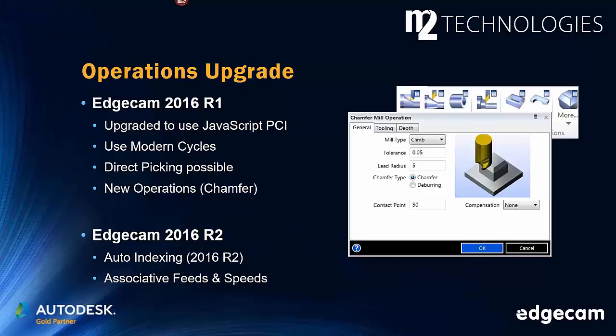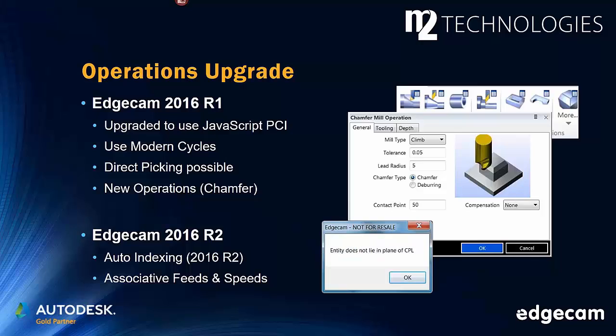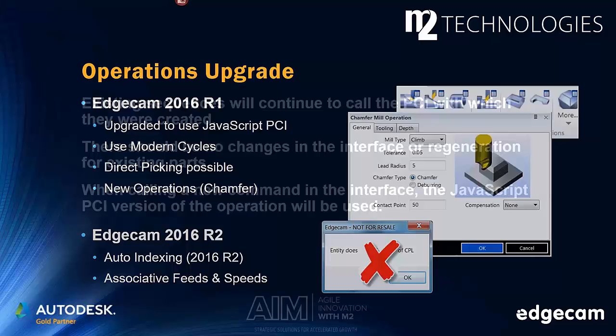Additionally, at Edgecam 2016 R2, auto indexing is added. What does that mean? Well, if you have a part where you're doing things in a 4 or 5 axis indexing capable machine or on a lathe with live tooling, in the past you had to position the tool to the work plane you want to work in before you could do the operation. If you didn't, you'd get the message that the entity does not lie in the plane of the CPL. You won't see that message anymore. The operations are intelligent enough to auto-index to the feature if needed. Just, again, save some time and effort. And feeds and speeds, you now have control of whether those should be associative.